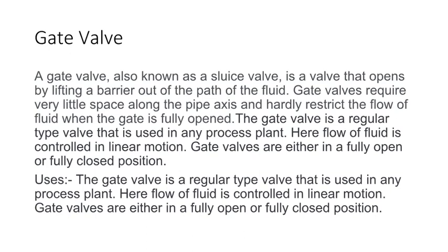It has to provide a good shut-off. It will not be used as a regulating or control valve because when we start to open the gate valves, the passage is slowly opened and similarly slowly gets closed.